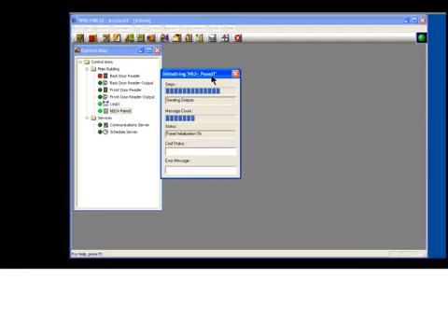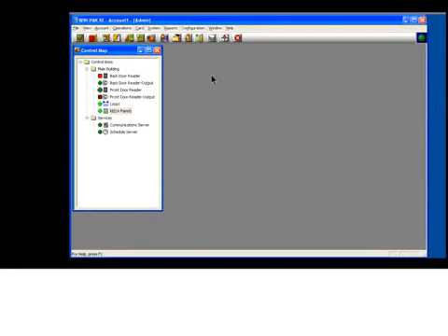What that means is for older systems that are out there, customers that are using the older Winpak software, they don't have to wait for a panel to be initialized when they're downloading cards for cards to actually function in the system. Now, at this point, we've got a valid working system. If you take a look on your control map, you'll see that we've got a door. And that door to the left of it has a circle with an icon over it. And if I move my mouse over it, it actually says entrance OK.